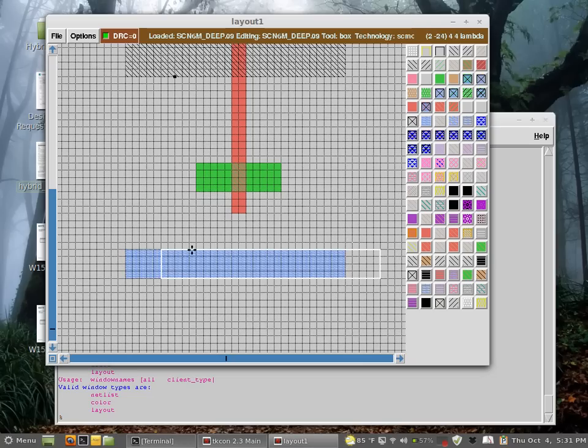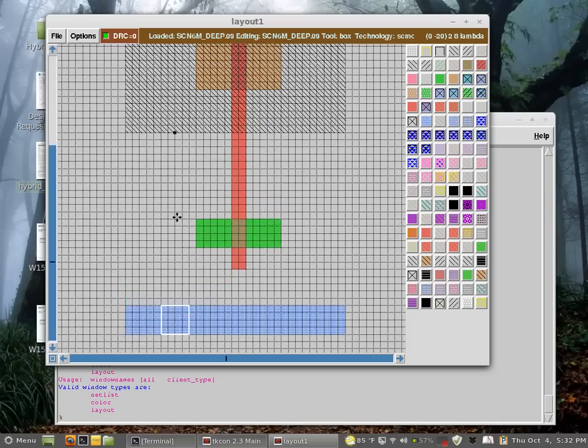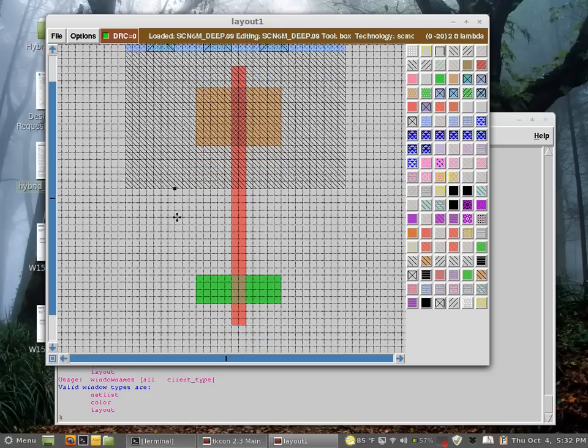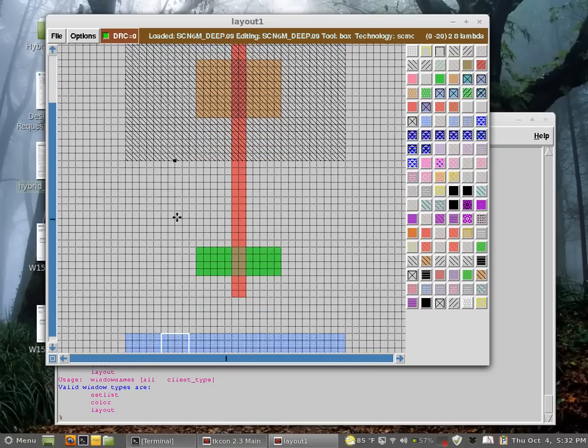And then I place my contacts. Should it be 3 times? What's up? Oh, the PMOS? No, we do it just 2 times. Although the mobility of holes is around 3 times less than that of electrons, 2 times will give us enough performance balance that we need.